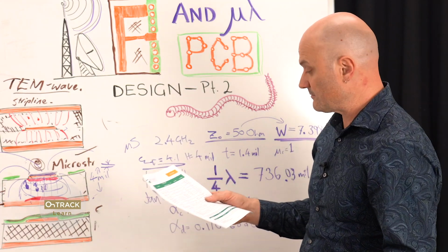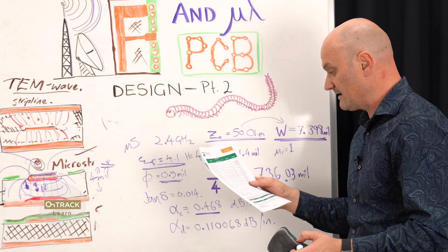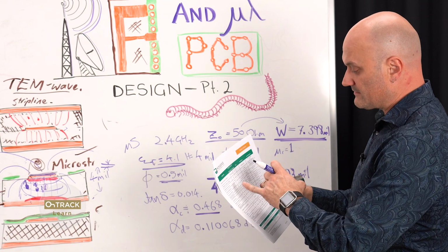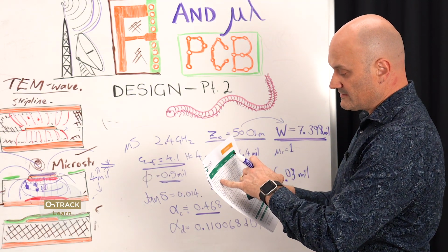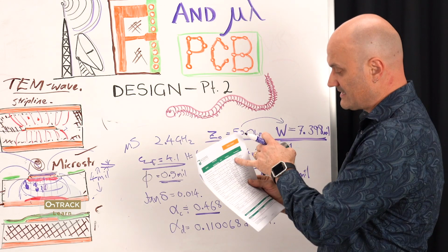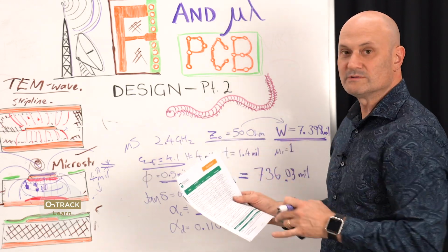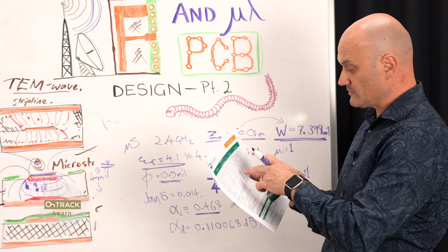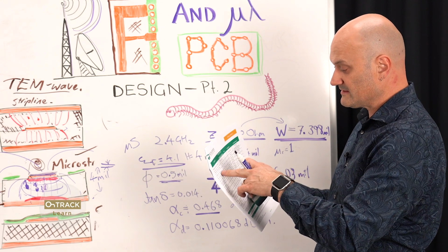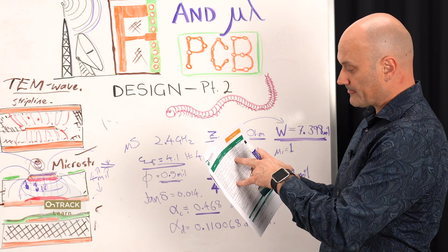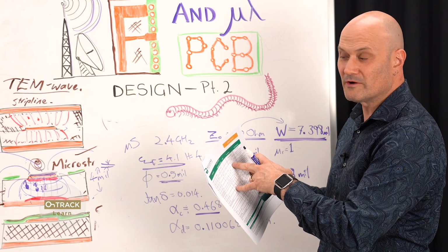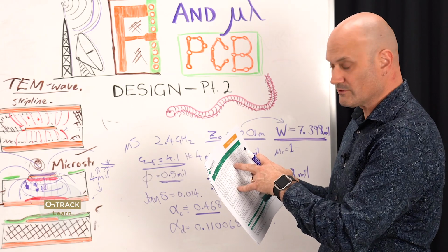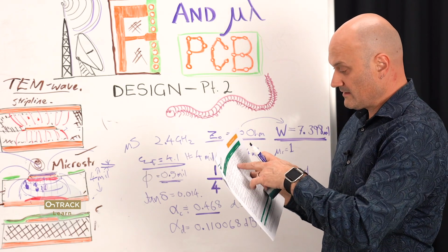This is just one example. So I have a Rogers data sheet here, and what I like about these ones, Rogers add things like their dissipation factor and dielectric constant are tested at the frequencies the material's intended to be used for. So here, dissipation factor tan D, they test it at 10 gigahertz, not 1 megahertz. It's several orders of magnitude higher frequency.